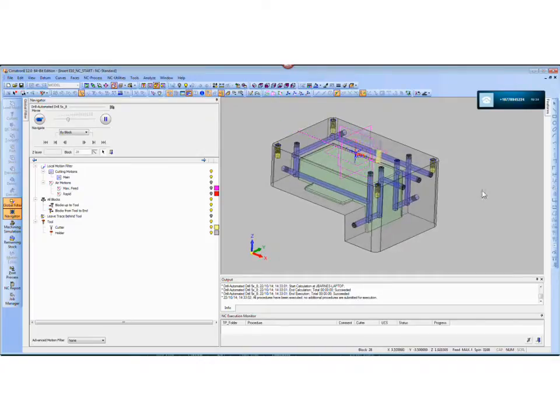And this is where we're going to start talking about automatic versus automated. The one thing that Cimatron does in this situation, this 422 diameter drill, as you know, is actually 0.4219. In fact, I think it's 0.42187. And so if you import this geometry through STEP or IGES, it might be 421 or 422 or 421 and 9/10.